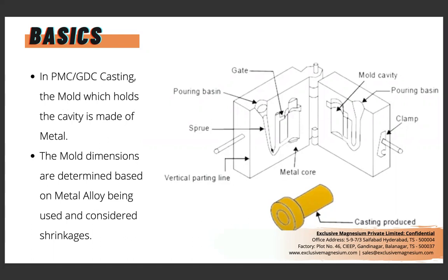Similarly, the shrinkage and cooling rate are quicker in a permanent mold than in sand, because it's made out of metal, and metal absorbs the heat quickly, so thermal conductivity happens fairly quickly. In that sense, you can create a lot more parts. All of this will be calculated by a manufacturer, who will tell you exactly how the die should be made based on the alloy you choose. You should expect the manufacturer to do that whole process.